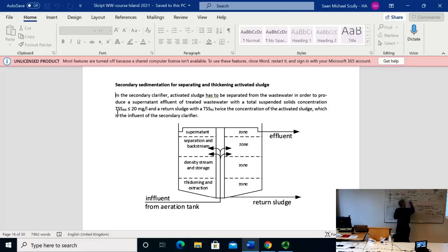The suction scraper is kind of like a Hoover, no? An aspirator, no? There you pump away the sludge from the floor, and this is of course where there's less sludge, the viscosity is lower, so you suck more of that thin sludge away, and then you finally suck water, and you have to suck more for sucking the thick sludge. Secondary clarifiers are mostly round, like shown here on the diagram.